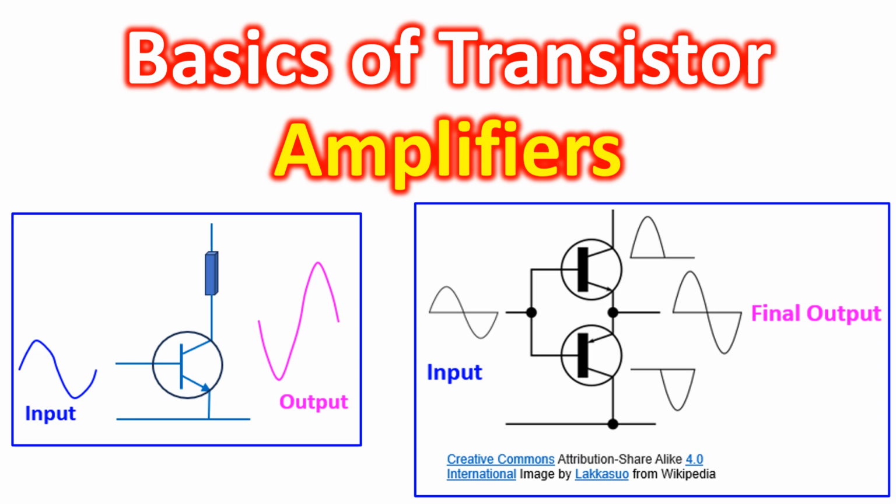Amplifiers used to amplify very weak signals and provide a drive to power amplifiers are known as preamplifiers. Power amplifiers are the output stages which provide large audio or radio frequency signal outputs. Power amplifiers are classified into Class A, B, AB and C amplifiers, depending on the region of the characteristic curve of the transistors at which they operate. Each type has a different application in electronics.